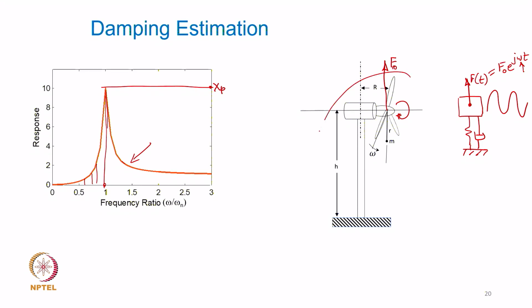Now, most of our mechanical vibratory systems, as you see here, are not going to have a dashpot hanging around here and there, right. They will have structural, inherent material damping. So, damping in most mechanical systems is going to be less than 0.1. It is a much lower level of damping, and so almost every time we say that omega p is very close to omega n, which means that the peak is observed close to the undamped natural frequency of the system.